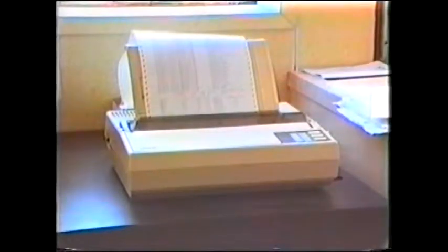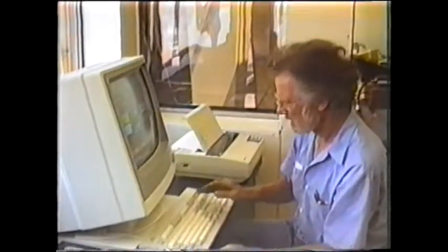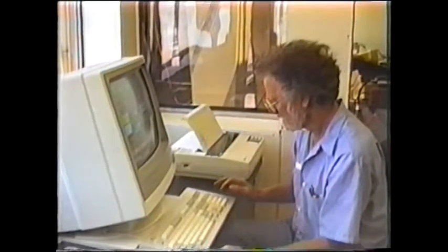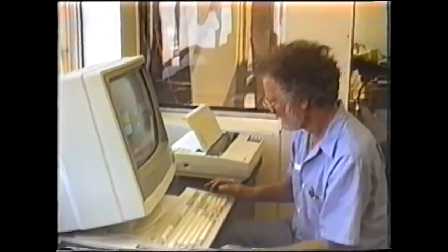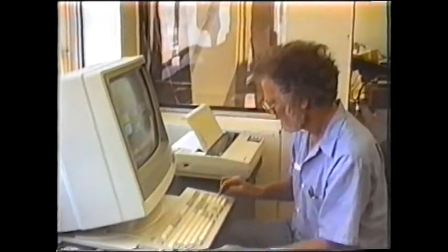3, the alarm is logged on the personal computer's hard drive along with the time and date that it happened. And 4, the alarm message is printed out. Along with the alarm conditions, every operator command is recorded on the hard drive. Using this history of events, one can get a report showing the complete plant operation for any time period.